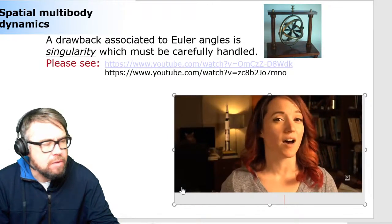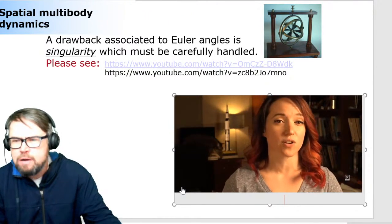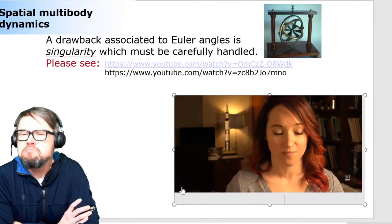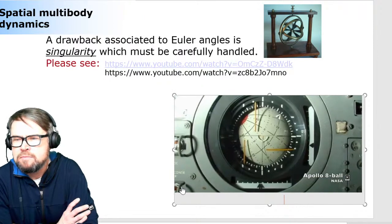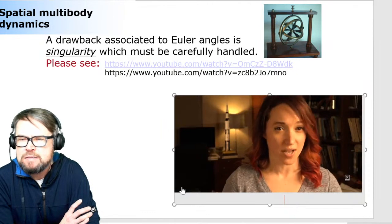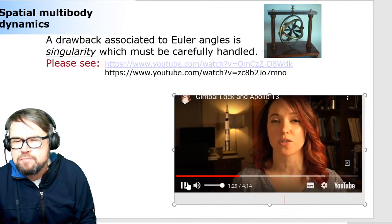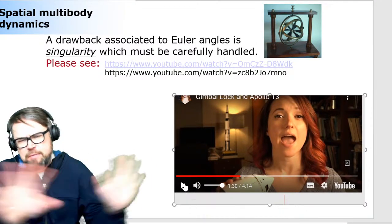The guidance platform was aligned on the ground before the flight, and of course it would drift occasionally during the mission. To compensate for this drift, astronauts would realign the platform using star sightings, but its use still remained, and it still gave the astronauts information on their attitude in space. The information from these gyros was displayed on the Flight Director Attitude Indicator, more commonly known as the 8-ball. It's the fact that there are 3 gyros involved in the IMU that makes gimbal lock possible. The 3 gimbals account for the spacecraft's 3 axes of motion, its axes of pitch, yaw, and roll. Because the IMU works in all 3 directions, the different order of rotation that I explained to you makes no difference.